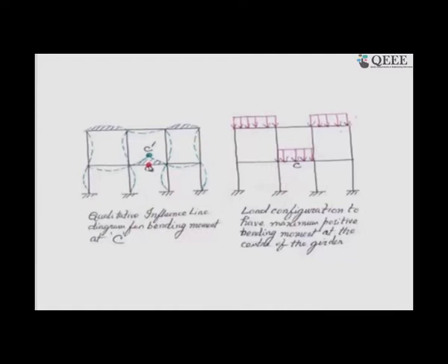So, this is also an indeterminate structure, and now let us destroy the moment carrying capacity of the beam in that plane. So, the beam at this point no longer takes the bending moment here. To do that, I need to introduce a hinge, an internal hinge there. An internal hinge is a moment release support. Suppose this hand of mine can release the bending moment one way. If somebody tries to bend my hand this way, he will never be able to do that, because my hand here is already giving way, that you can bend it, no problem.